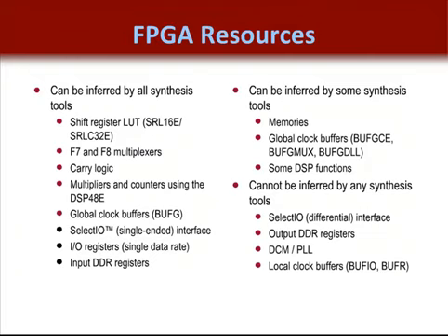One of the best ways to determine how to infer a resource is to go to support.xilinx.com and open the XST user guide. Now this is also associated from the ISE software. You can get it there from the help menu as well. And then do a search for SRL coding techniques, and you'll find examples of how to infer the shift register LUT. Now this user guide provides numerous examples of a wide range of dedicated architecture resources in the FPGA and shows you how to infer the best FPGA resources. So be sure and check out the XST user guide.